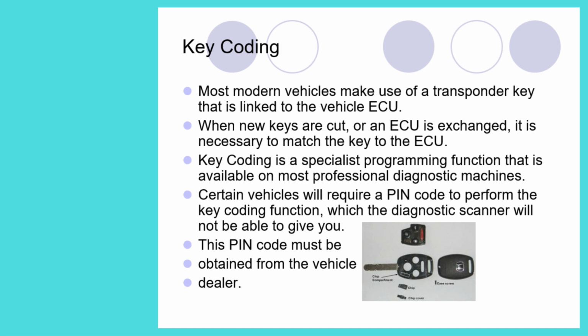Key coding. Most modern vehicles make use of a transponder key that is linked to the vehicle's ECU. When new keys are cut or an ECU is exchanged, it's necessary to match the key to the ECU. Key coding is a specialist programming function that is available on most professional diagnostic machines. Certain vehicles will require a PIN code to perform the key coding function, which the diagnostic scanner may not be able to give you. The PIN code is usually obtained from the vehicle manufacturer.